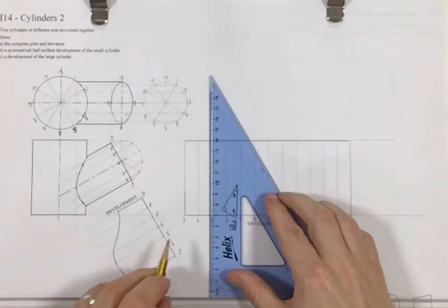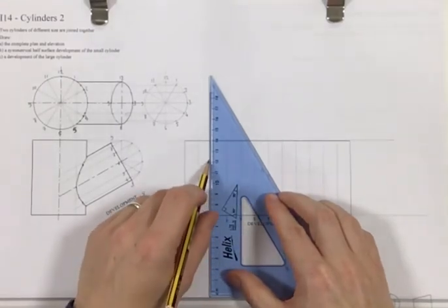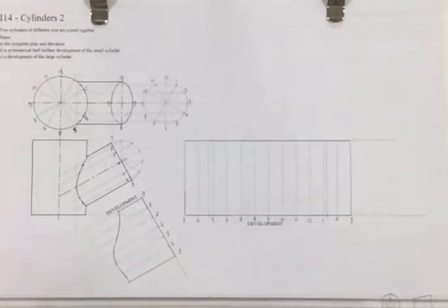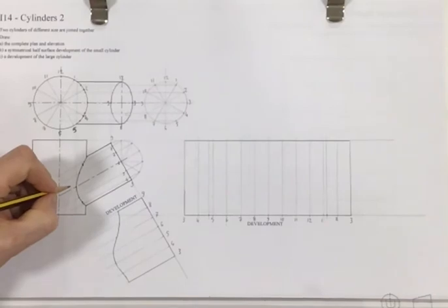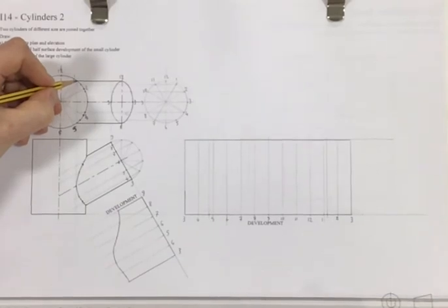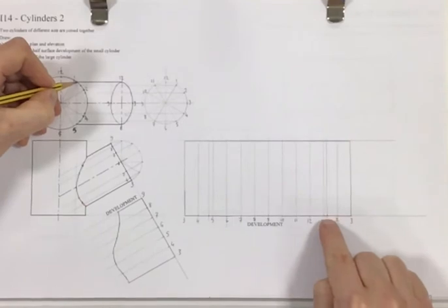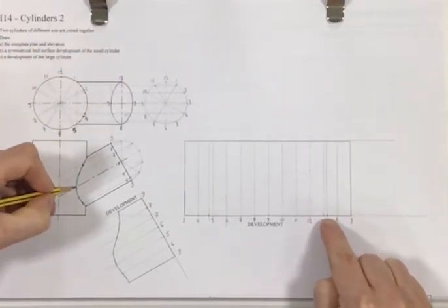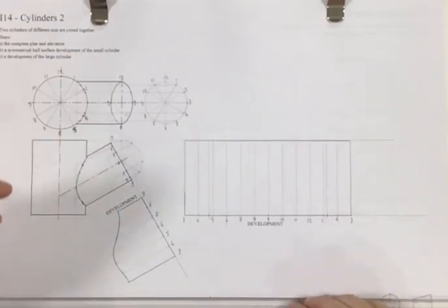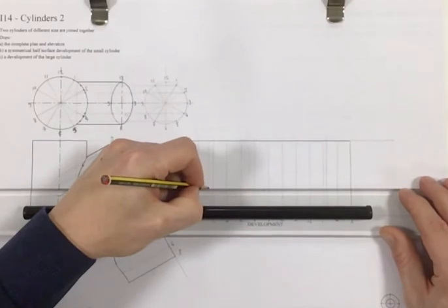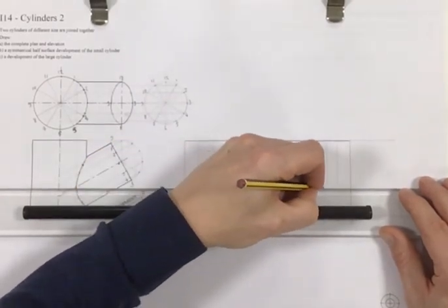Now at that point, I want to just bring another working line up like so. What do we know? We know that at that point, that feature's there. So this new line that we've put in between 4 and 5, and in between 1 and 2, is going to feature that at that height. So we can then project that across onto that new line that we've created. That one, sorry.